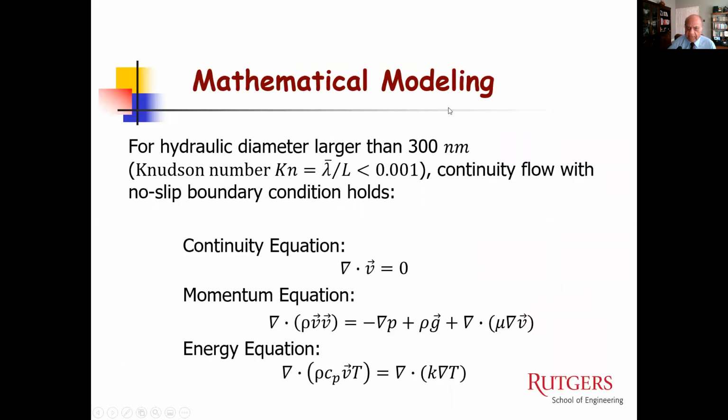The mathematical modeling is fairly simple when you're dealing with water or a liquid, because you can still use the no-slip conditions. And the basic equations are very similar, except that you do need much finer mesh sizes. And you also have to worry about viscous dissipation, pressure increase, and so on, pressure drop in the channel.